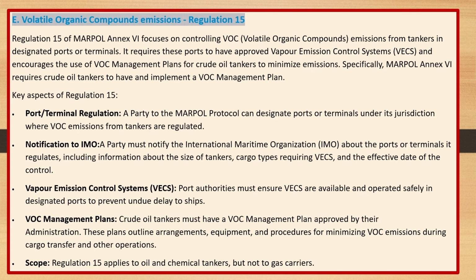E. Regulation 15 of MARPOL Annex VI focuses on controlling VOC, volatile organic compounds, emissions from tankers in designated ports or terminals. It requires these ports to have approved vapor emission control systems, VECs, and encourages the use of VOC management plans for crude oil tankers to minimize emissions. Specifically, MARPOL Annex VI requires crude oil tankers to have and implement a VOC management plan. Key aspects of Regulation 15.